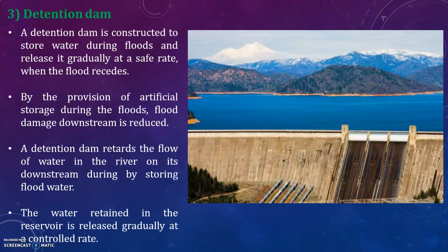There are usually two types of detention dams. In the first type, water is temporarily stored and released through a suitable outlet structure. In the other type of detention dam, water is not released and no outlet structure is provided. Instead, water is held in the reservoir as long as possible. This held water seeps into pervious banks and foundation strata.